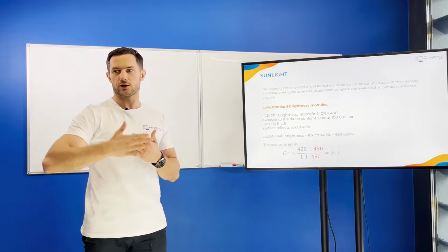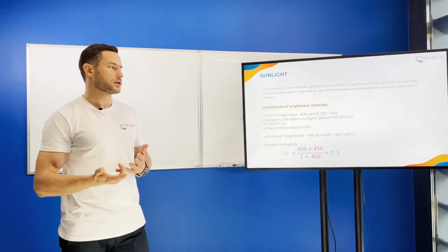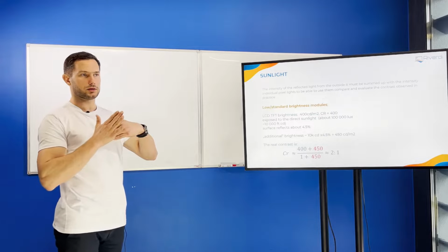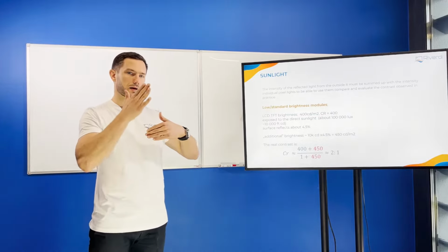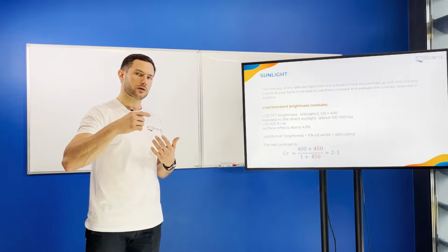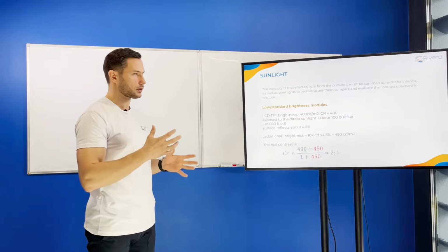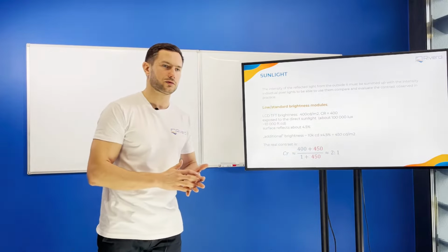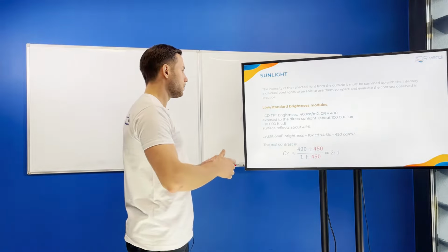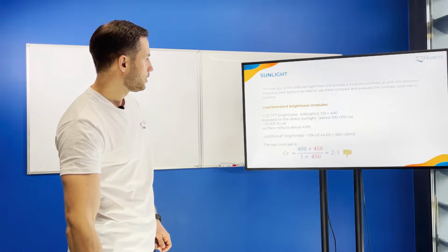It's not only a display that we have outdoor, but we need to protect the display. So usually we add additional glass. Often this additional glass is not optically bonded to the surface of the display, so we have air in between. That means we have more reflections. We have them from the glass itself, from the glass to the air, and from the display again. So sometimes we have even 10% reflections, or even more. That's why we need to increase the brightness as well. It's not that easy to handle.